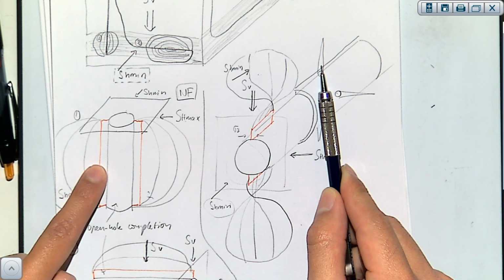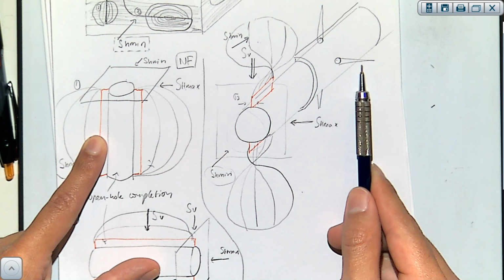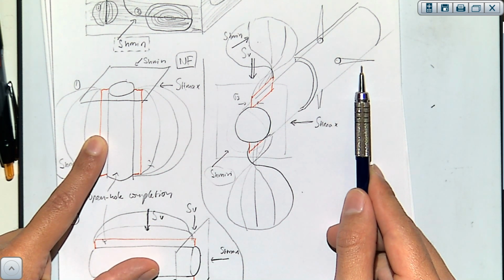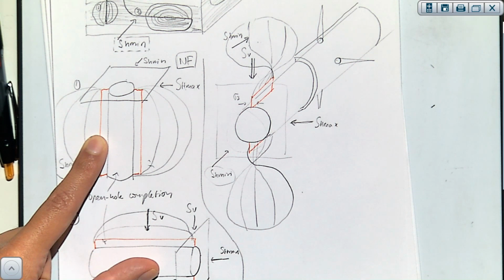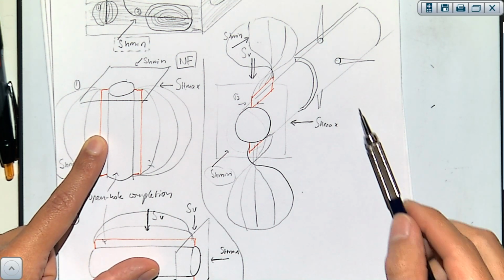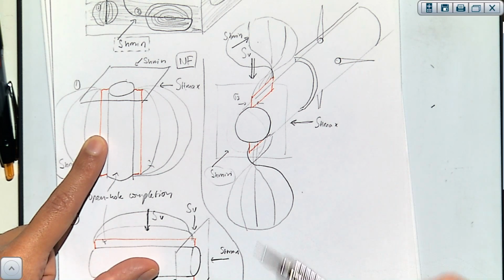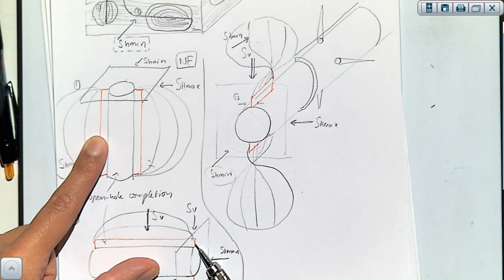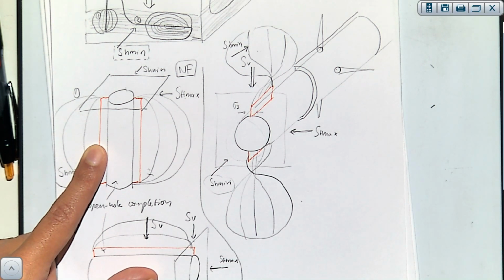It's equal to this one, and it's equal to that one. And in those, when you start pressurizing the perforations, then your tensile fractures are going to be located at these two regions. And now, if your hydraulic fracture continues to grow, it's just going to continue on that plane.